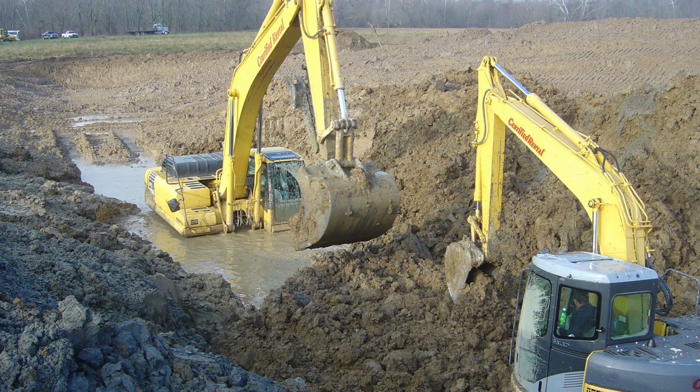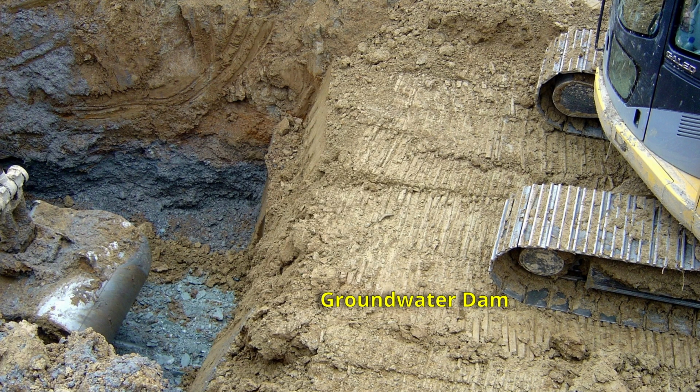The operation required close coordination between everybody who was involved to make sure that the gravel was removed before the core trench was filled and compacted with silt clay soil. Here it looks like the small excavator is almost building a road in the bottom of the core trench. The silt clay was compacted to an elevation above that of the gravel and the sand in the core trench, which were more likely to collapse.